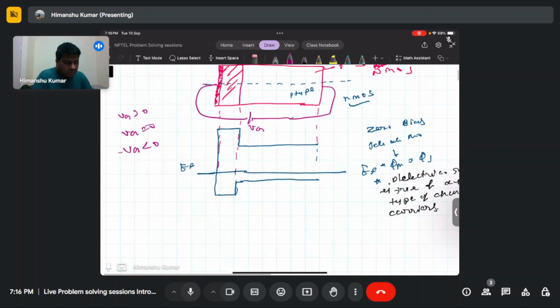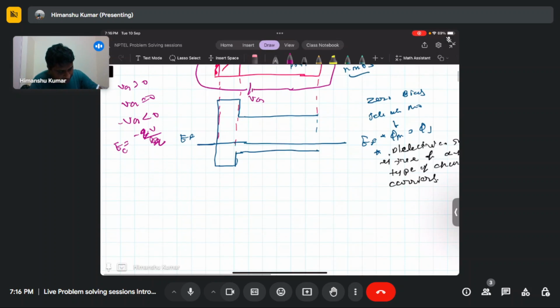So what happened is, since EC is minus QV, so EC is minus QV, and that potential, you can write V is equal to EC by Q. EC is basically energy, and potential you define with respect to unit Coulomb charge, so you need to divide by the Coulomb charge, and that you can define in volts. So when you apply a gate voltage, it pulls the level up or down.